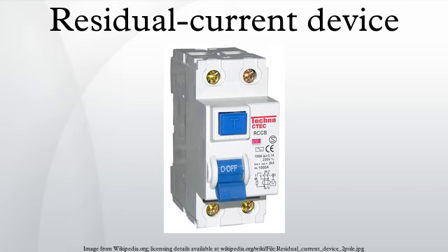circuits. The current edition of the regulations requires that all socket outlets in most domestic installations have RCD protection, though there are exemptions. Cables buried in walls must also be RCD protected. Refer to 17th edition Amendment 1 effective from January 2012. Provision of RCD protection for circuits present in bathrooms and shower rooms reduces the requirement for supplementary bonding in those locations. 2 RCDs may be used to cover the installation, with upstairs and downstairs lighting and power circuits spread across both RCDs. When one RCD trips, power is maintained to at least one lighting and power circuit.